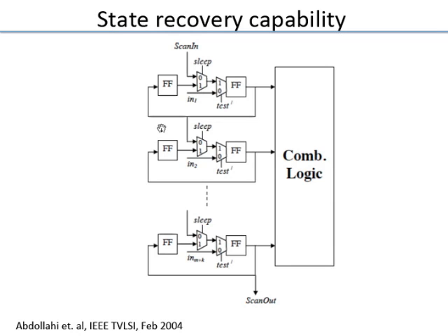No, you go into standby state in a single cycle, but the information which is stored here after manufacturing test... Actually, in this kind of a setup, when the chip is powered up, somehow the standby state vector has to be entered here through the serial interface. Maybe there is a BIOS ROM, or some ROM. So at the beginning it reads, and all the setup is done. Then as the chip is running, it goes into standby state. From here it goes here. When it comes out of standby state, from here it's put back here. So it's ready for the next standby state.